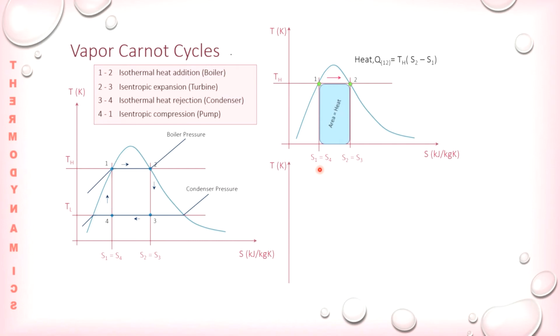For heat rejected, you still have to remember that most of the time we need the net work out to calculate the cycle efficiency, or the Rankine efficiency later on, or the Carnot efficiency, etc. So it is very important for us to know how to obtain the heat supply and the heat rejected based on the TS diagram for heat, and based on the PV diagram for work.